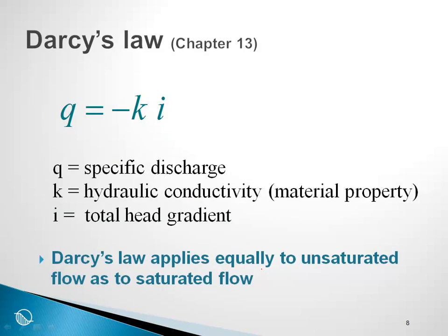So here's Darcy's law, and it is a very basic, simple law. Fundamentally, it says that the specific discharge is proportional to the total head gradient. i is the gradient. The constant of proportionality is the hydraulic conductivity, and it is the material property. Now in SEEP-W, we use Darcy's law both for unsaturated and saturated conditions.